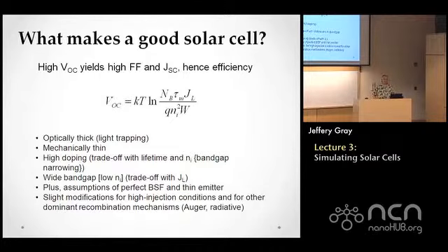But you can get close to that, and there are some tricks you can pull. It's called light trapping. For instance, if you texturize the front surface, instead of the light coming straight in, it gets diffracted and comes in at different angles, and is more likely to get total internal reflection. If you put a mirror on the back, the light that hits the back bounces back, and you can get multiple passes, dozens of multiple passes in a good light trapping design.